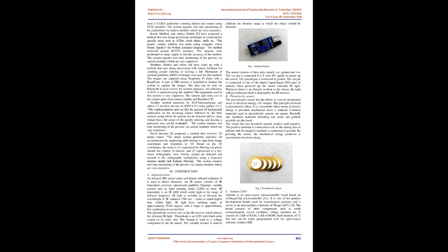Another approach using IR sensors was proposed by Jyotibasu M., Akash B., and others. IR sensors play a vital role in identifying objects. In this method, two IR sensors are placed adjacent to each other which detect the visitors. The logic behind the working of the counting process is simple: when the person crosses the sensor near the door and then the sensor away, it recognizes an increment in count. Apart from being a bidirectional counter, this method can be used to control home appliances and helps in consuming less electricity.